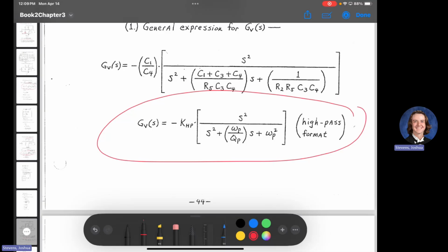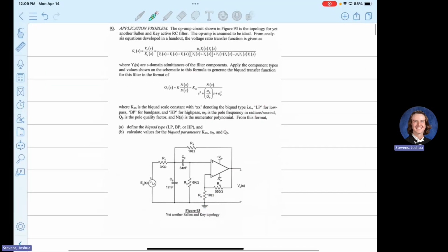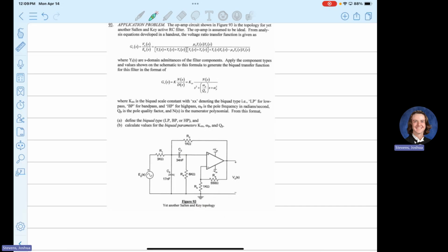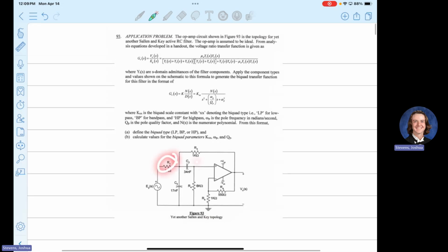Okay, so I'm going back to here. As you can see, we have an R1, a C2, an R1, a C2, an R3, an R4, and a C5. We also have these resistors RA and RB. I'm curious, since y'all haven't really done op amps, if you can answer this question. What type of feedback is this op amp? Positive feedback? Are you sure? Well, actually, it's multiple feedback. That was a bad answer.